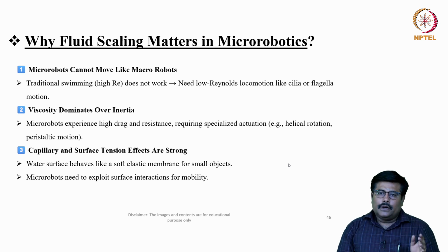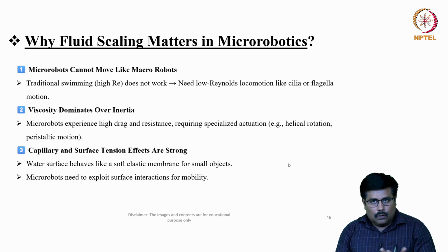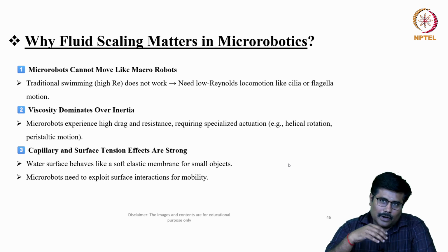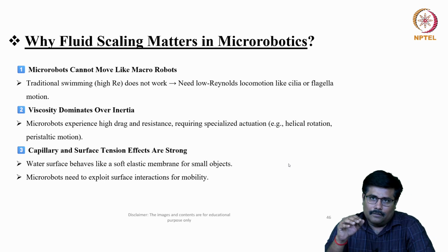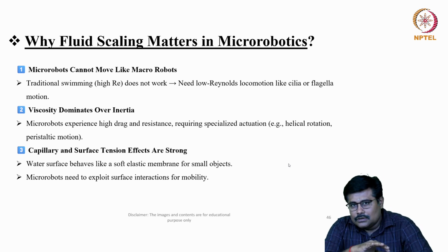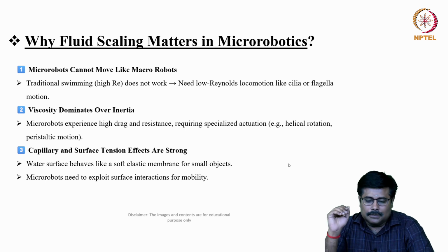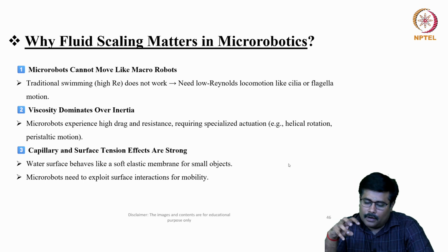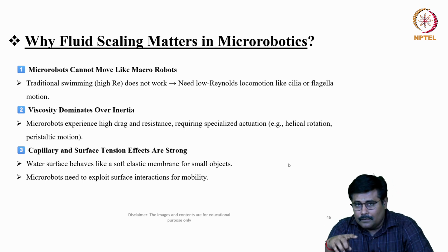Similarly, from the viscous-dominated over inertia point of view, when these micro robots try to move in such a liquid domain, they experience high drag and resistance. In fact, this also has a direct impact on power consumption. So there is a need to go for specialized actuation. That is what we have seen in our first slide also.